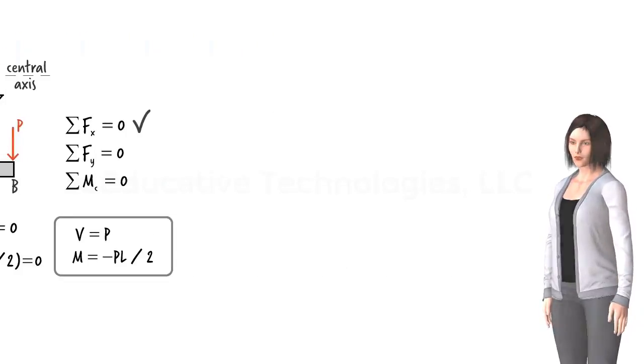In order to calculate the shear force and bending moment at a point in a beam, it is necessary to conceptually cut the beam at that point and draw the free body diagram for each beam segment. Here, it is important to recognize that any time we cut a beam, we need to show the beam's internal forces at the cut point. So, if we cut this beam at its midpoint, point C, we end up with two beam segments, the left segment and the right segment.